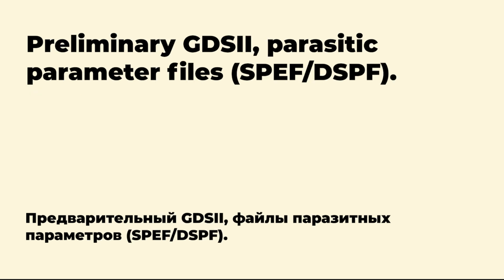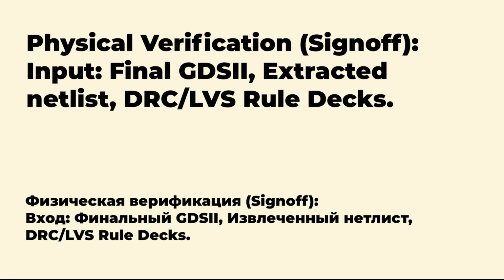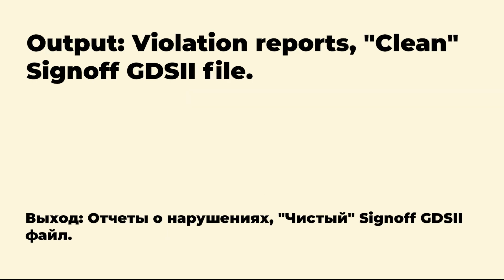Preliminary GDSII, parasitic parameter files, SPEF, DSPF. Physical verification, sign-off. Input: final GDSII, extracted netlist, DRC, LVS rule decks. Output: violation reports, clean sign-off GDSII file.